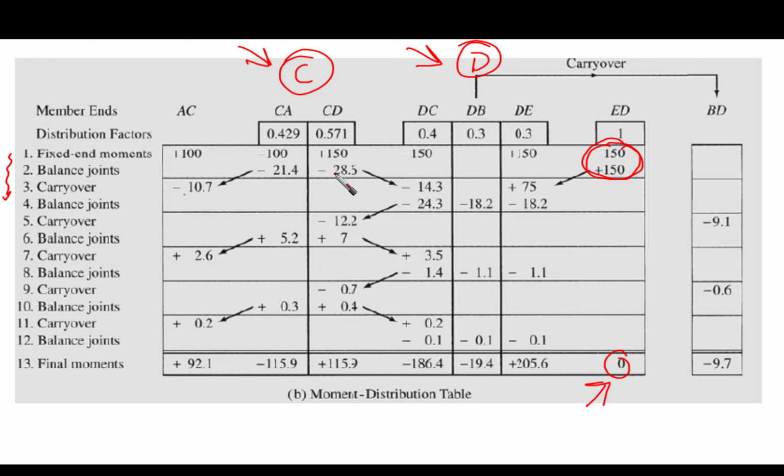So now this is the general procedure for it. Let's go with the detailed procedures. So first of all, we're going to balance the joints. It is joints here, okay? It means that C and D together. We are going to balance the 2 joints at the same time. As you remember, I have explained this in 2 videos before, which is the practical implementation of the moment distribution. Instead of balancing C in one step and then going to joint D and balancing it and then going back to C and so on, we are balancing both together.